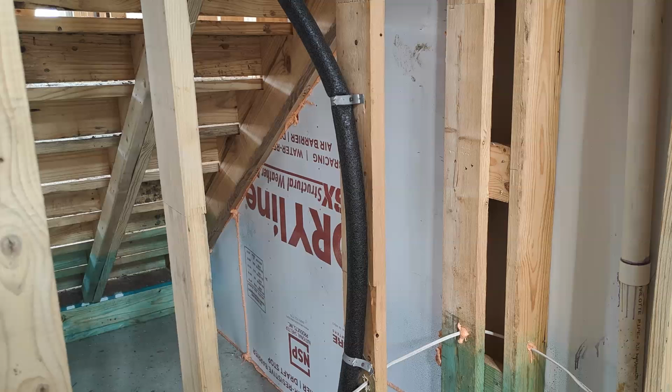That used to be the case. It used to be used before in previous building styles. It now needs to be replaced. I still see builders allowing this to be used, and third-party energy companies are not calling this out. It is imperative that you have an interior air barrier as well as an exterior air barrier.